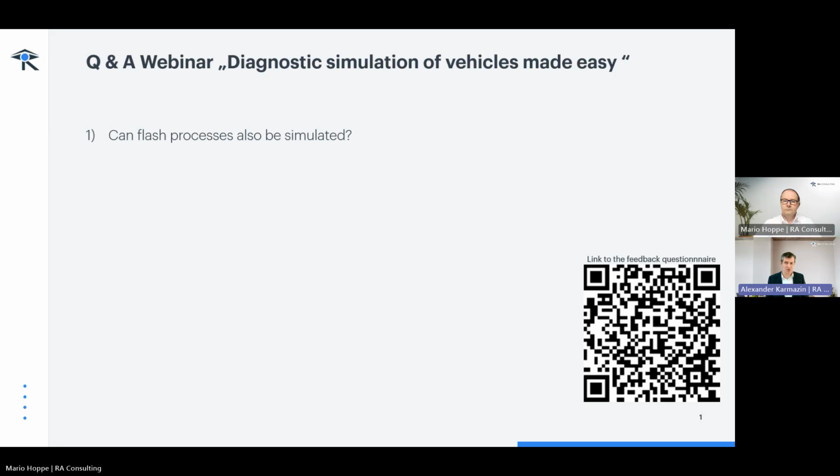You define kind of a request pattern and say all requests to the transfer data service will be answered with such a positive response, and it is really easy to do that, and it's the most comfortable way to do that, unless you want to simulate some error behavior. Then in that case, you will need to handle these requests for service 36 separately.